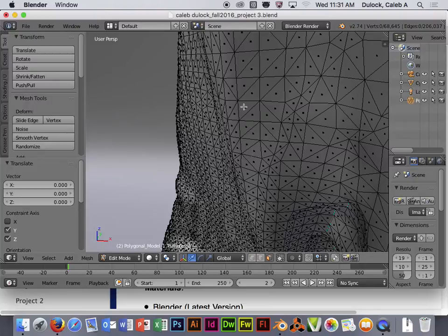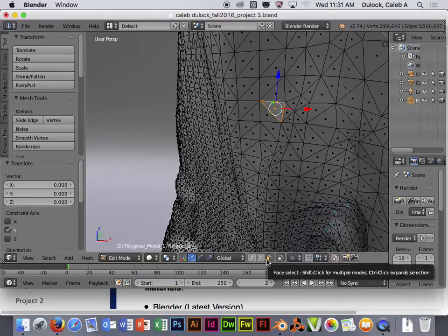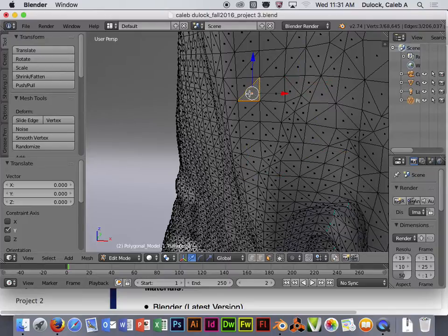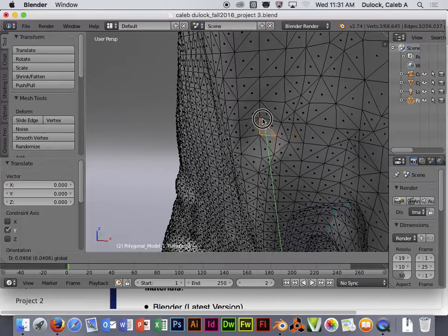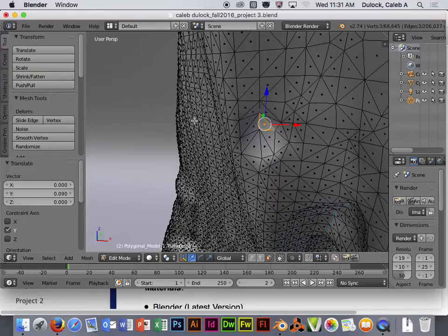The last one does what's called faces. So that's actually grabbing a whole polygon structure. When you activate face selection, which is the cube with the giant orange face on it, that one actually changes the look of your model on screen to showing all these little dots centered over each polygon. So you can click on each one and you can actually manipulate the whole polygon and any connected edges that are connected to that particular group of imagery.